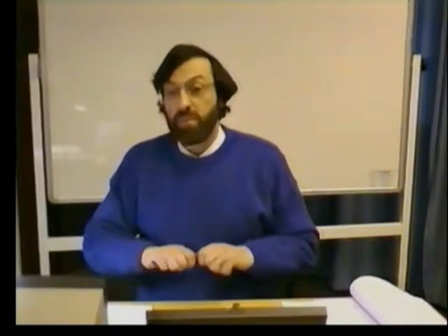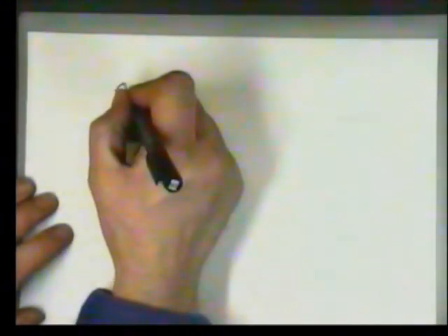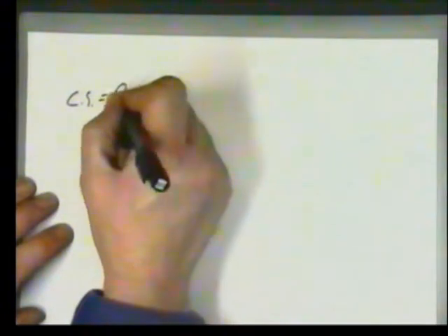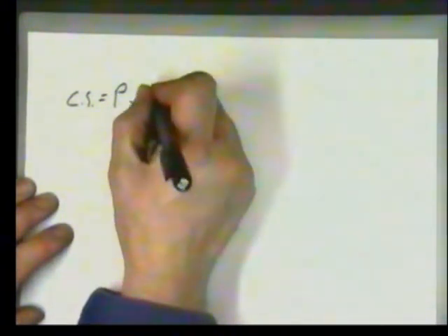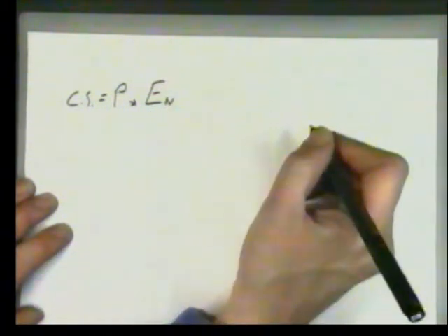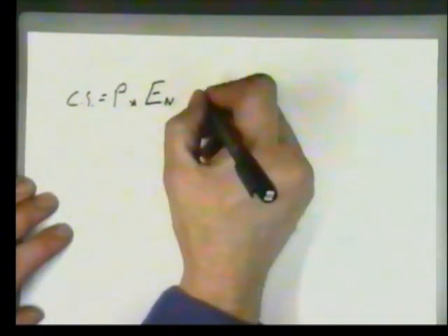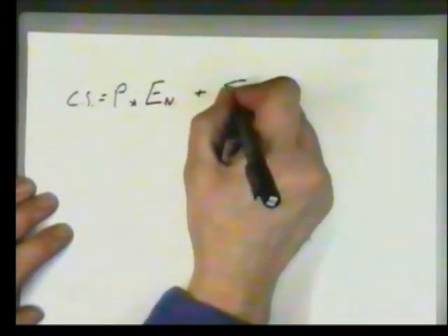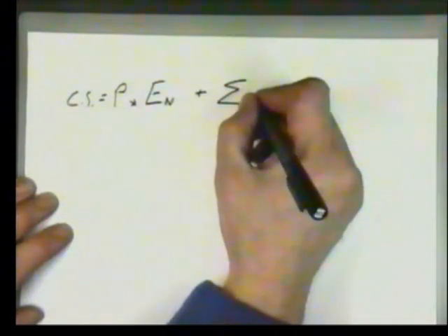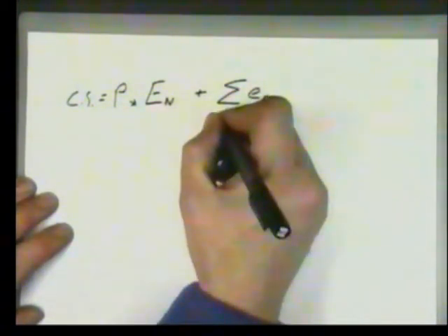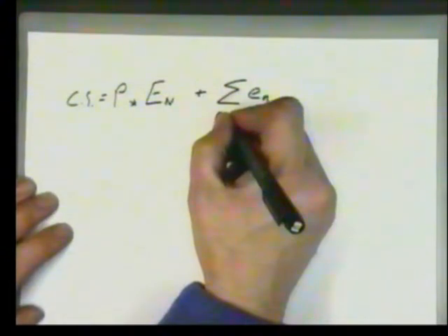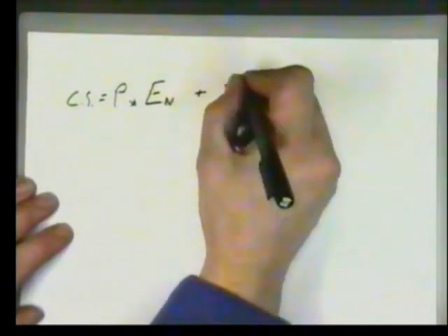And instead of using an integrator, let us think of it as a sample data system, a series of discrete samples. So now I'm going to say our control signal equals our proportional term times our sample of E at time n, plus a summation of all the samples of error from some time n minus 128 to n, say the last 128 samples.